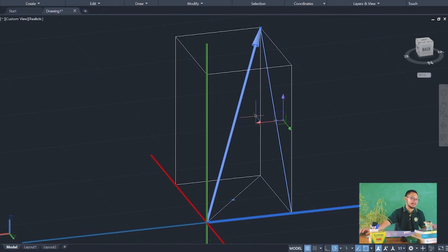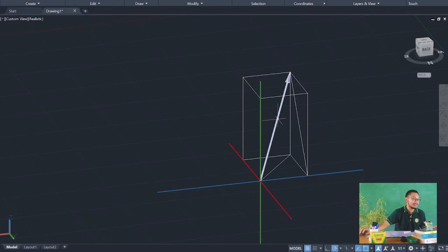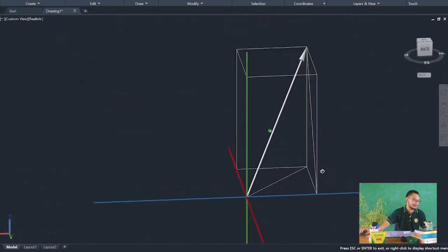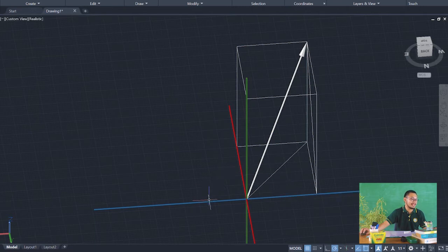Okay, for our beta. But in this case, I said that it is from the positive y-axis to the direction of the force. So, what will you do? We already know that this is 180 degrees. So, in this case, in our problem, since it is on the negative side, and I said that beta is from positive y to the direction of the force, therefore, all you have to do is 180 minus the angle that you solved to get beta. Okay? So, now, how about your gamma?